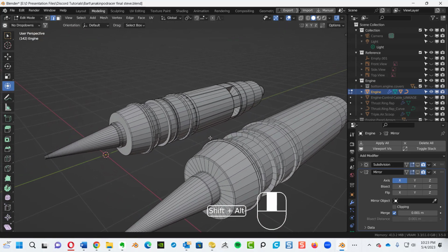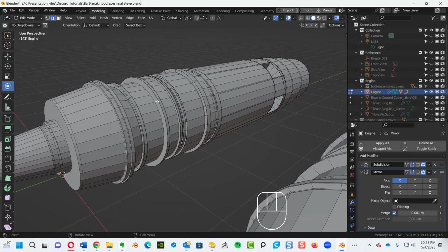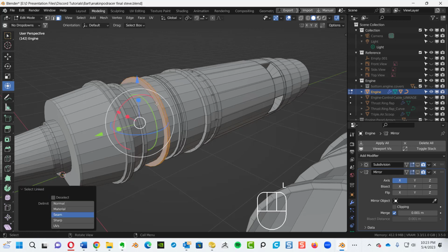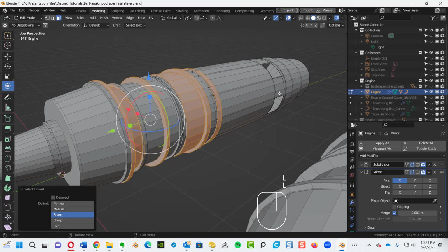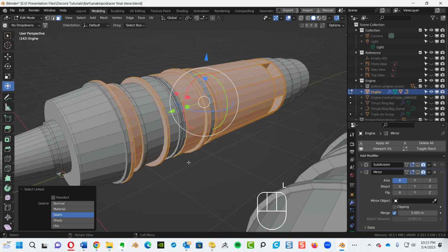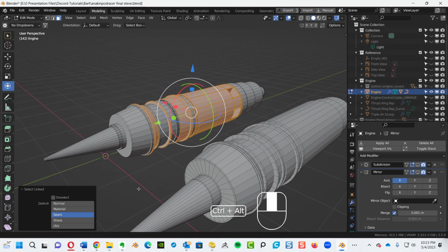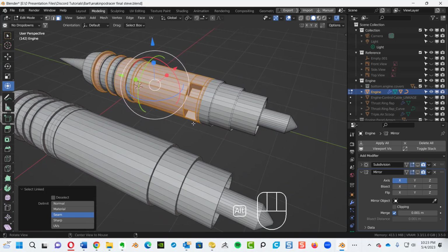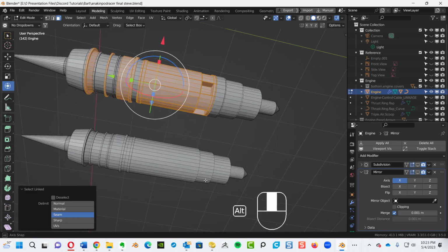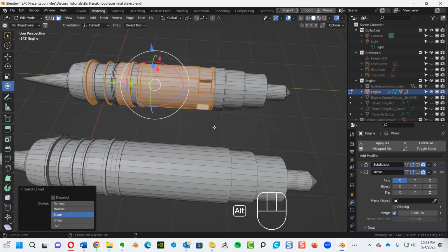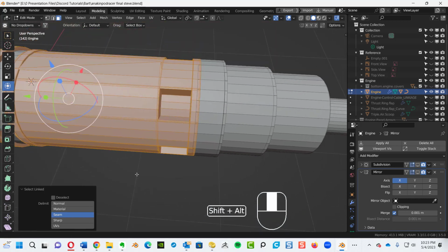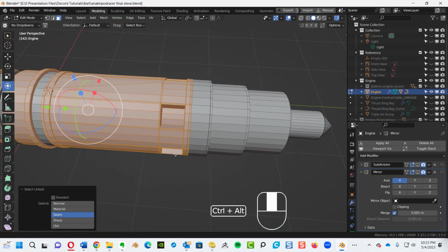Now with yours, you have a whole bunch of individual rings in here. Let me go to this number 3 key on the keyboard for face editing mode. Hit the L key. See, and you got all these individual rings. They're all individual geometry pieces. Okay. Actually, before, let me kind of replicate how you would do the squares there. So I'm looking at your squares right here, or the insets in here for the square insets. I'll just do one for now.